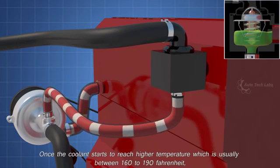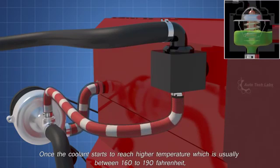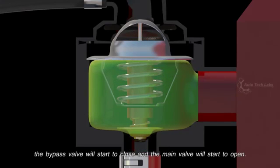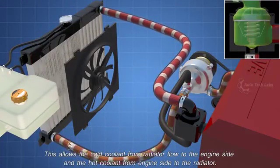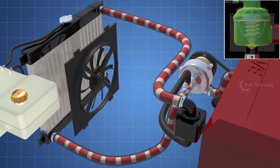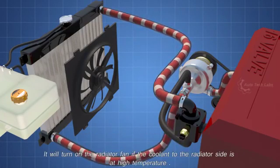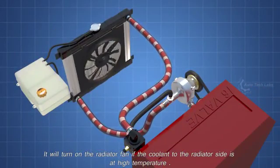Once the coolant starts to reach higher temperature, which is usually between 160 to 190 Fahrenheit, the bypass valve will start to close, and the main valve will start to open. This allows the cold coolant from the radiator to flow to the engine side, and the hot coolant from the engine side to flow to the radiator. In most cars, the coolant temperature sensor is located near the thermostat housing. It will turn on the radiator fan if the coolant to the radiator side is at high temperature.